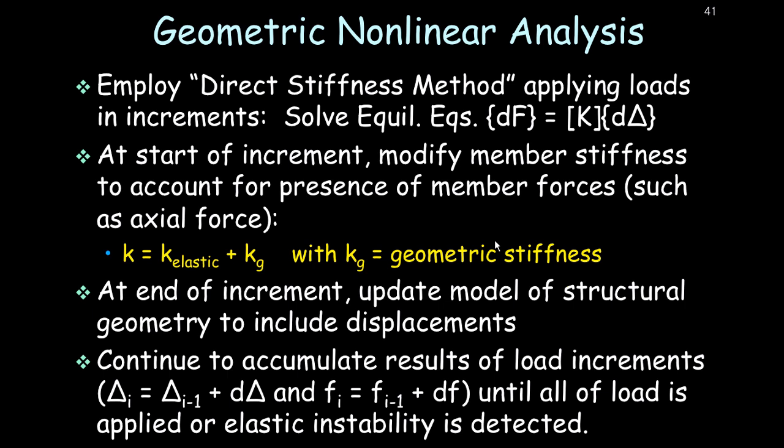And the other thing that most of these programs are doing, and again, you're not even touching it, you're just watching it in action, is they're doing it iteratively. All right. So they're putting either some of the load on or all the load on, and they keep iterating on that load until they get equilibrium. And it's not until that point that the program stops and tells you that, yep, we've got there, this is the solution. And so the programs that include an iterative solver are real nice. It's sort of like getting a car that's turbocharged or whatever. They are real nice because their solver is going to keep iterating until equilibrium is in fact defined on the deformed shape. And so you don't need to worry about the size of the load step.